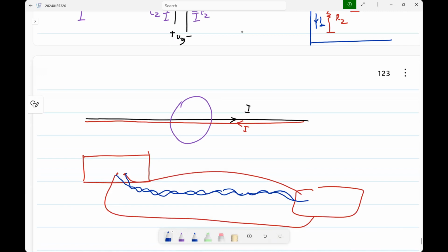So if you make circuits, you should try to make sure that, especially of course, the longer the wire, the more important this becomes, the current and the return path should be coincident as much as possible. Essentially, you should not have current loops with large areas. If you have current loops with large areas, they will radiate out magnetic field. They'll also be susceptible to magnetic field.